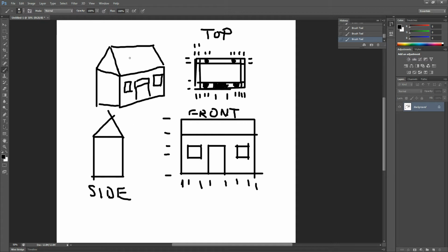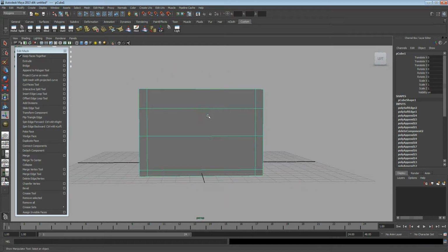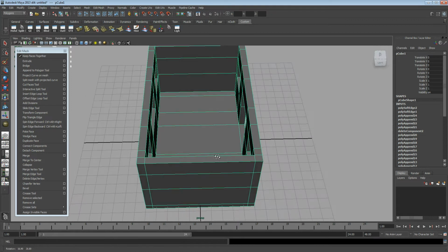So before we build our specific roof, we need to make sure that this is constructed in such a way that there is a triangle at the side. So going back to our 3D model, we need a triangle, and at this point we are lacking a division. So what we can do again, insert Edgeloop Tool.